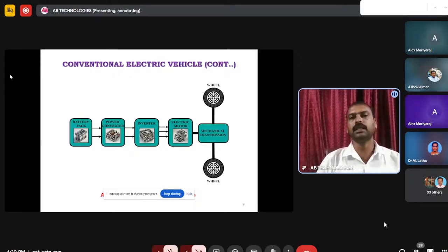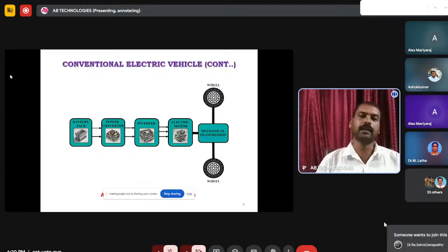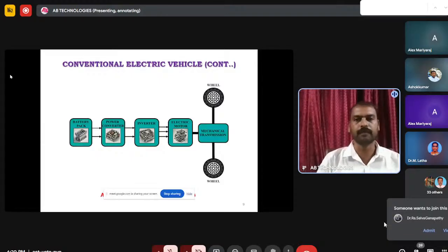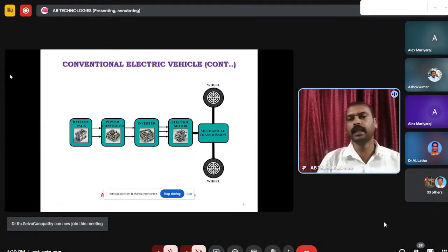From the 10 milliseconds, if you calculate the frequency, we get 1 by 0.01, which is 100 Hz. That is the harmonic actually, the second harmonic. So harmonics means integer multiple cycles of the fundamental frequency, and it creates distortion in the input current.